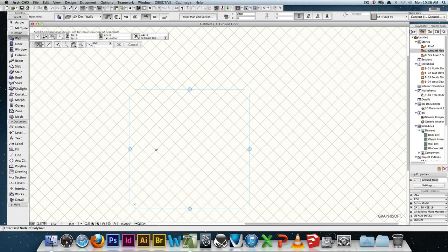So you can see we've got a huge amount of power just with the grid alone. And I'll go over how you snap to this grid. But it means that we can set up our own grids. They can be all sorts of different weird custom sizes. You can change them whenever you like. So if it's just one part of your site that has a kind of a grid type layout, and you want it to be a specific size, you can move the origin, rotate it to align to that part of the site. You can change how that grid appears. It doesn't have to be square, it could be oblong, and we can snap to that.